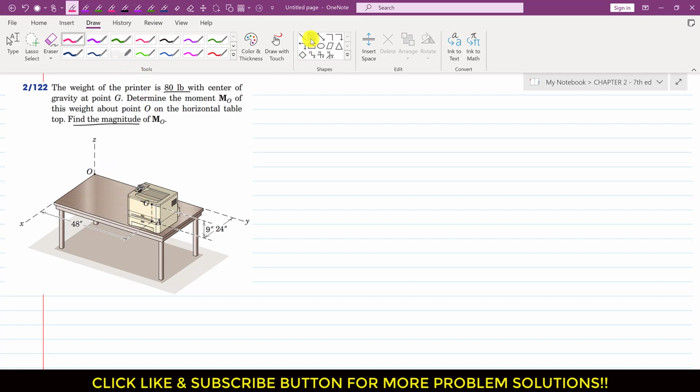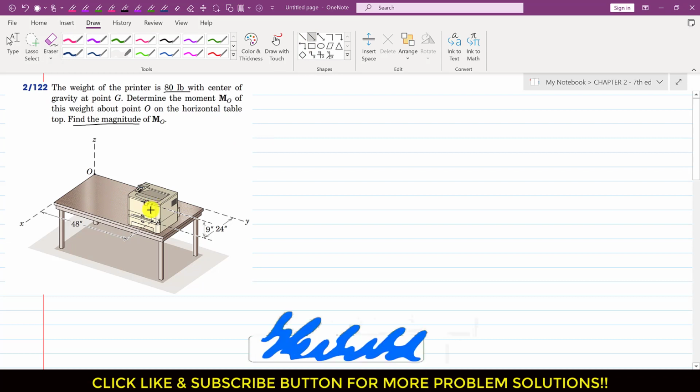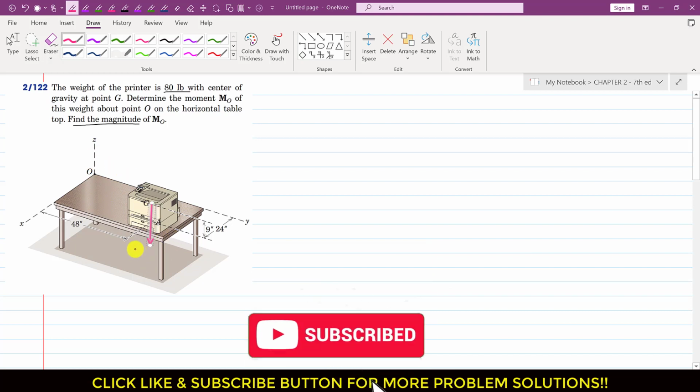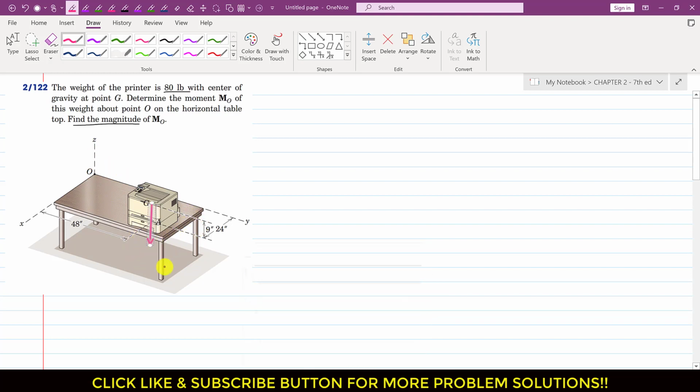If I draw the weight of this printer, it will be acting vertically downward in the negative z direction. This is our positive z axis. So the weight will be acting vertically downward in the negative z axis, and its magnitude is 80 pounds. So we have to determine that moment about point O. If we use the cross product method, then we have to write R cross F, or R cross the weight of the printer. So we have to define the moment arm.